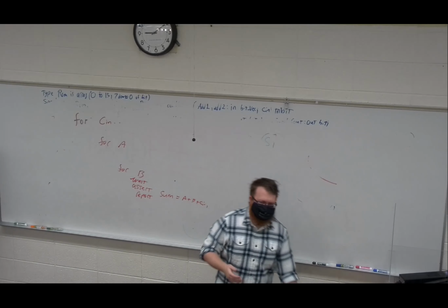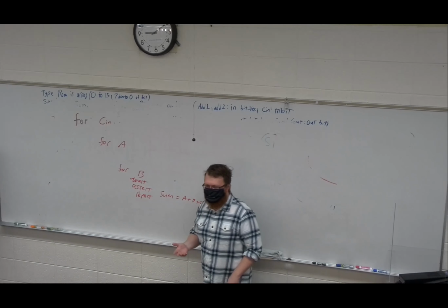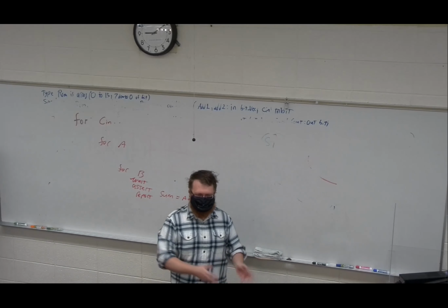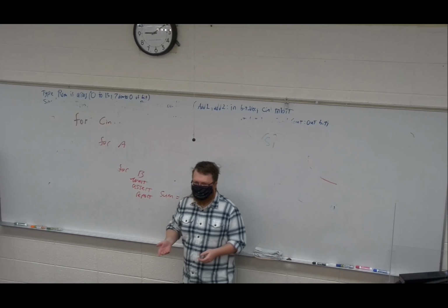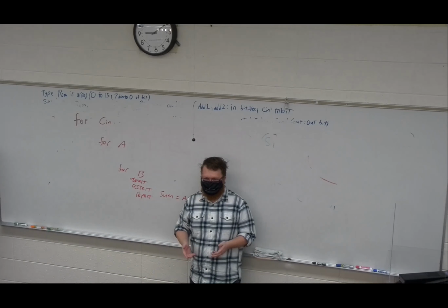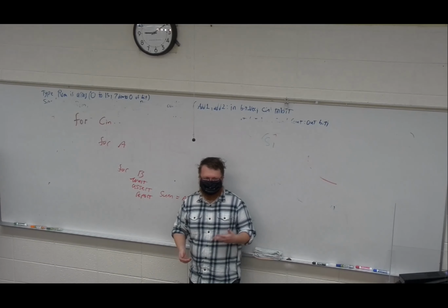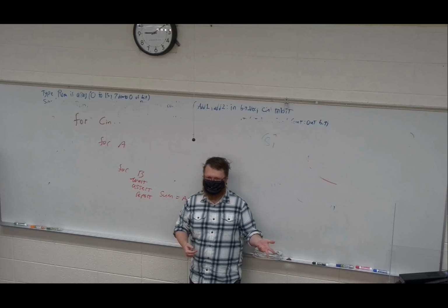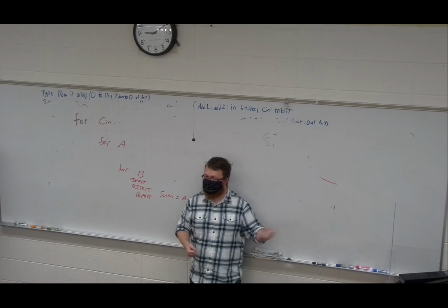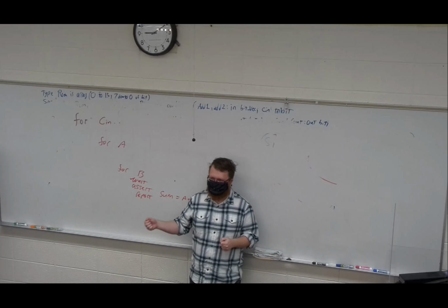That's the first step in the debug. The next step is, we all know by this point, that just because it simulates correctly, or apparently correctly, doesn't mean it's going to work on the board, right? Some of this has to do with things we can write in code that aren't synthesizable. The big one is counters, right? You think you've initialized the counter, in simulation it works, but it doesn't work in implementation.